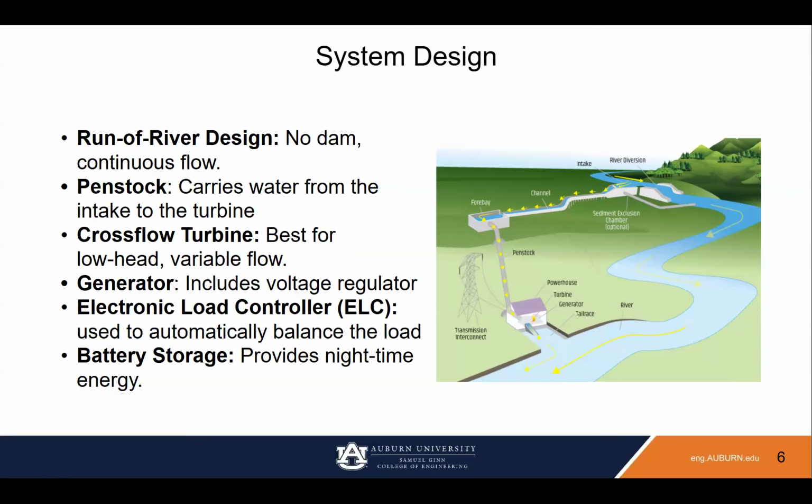They are also quicker and cheaper to build than the large dams that we see and study. But the important downside to note about these is they lack substantial storage. So they produce less power and they're not nearly as flexible during dry seasons or if there's peak demand and things like that. Many of these run-of-river sites, while we want to maximize head height, are considered low head environments so that the drop from intake to turbine is relatively small. So this is under about 20 feet.